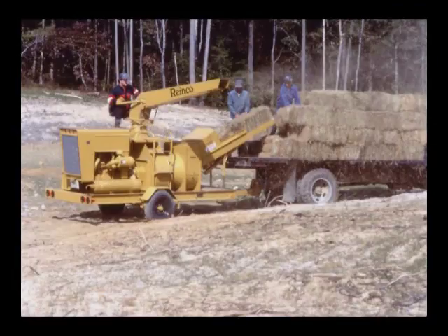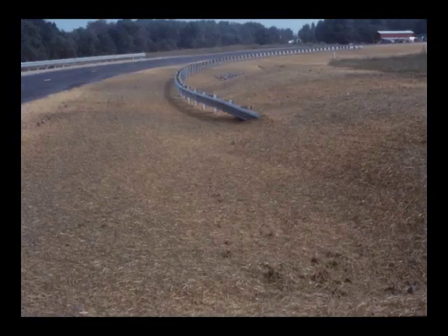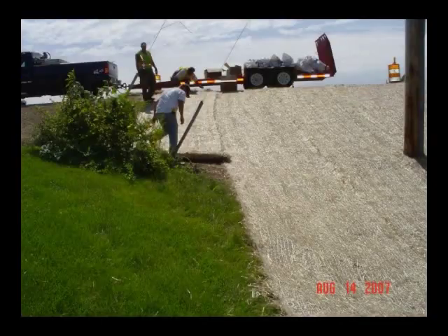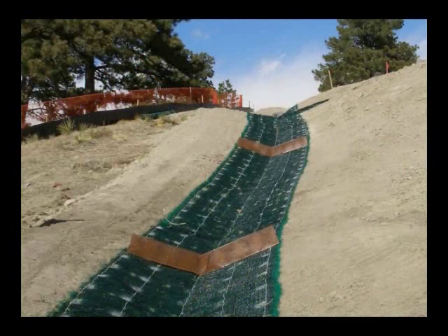On slopes, windy sites, or areas adjacent to roads, mulch must be anchored using netting, a tackifier, or a mulch anchoring disc. Many different combinations of mulch, tackifier, fertilizer, and seed can be applied with a hydroseeder. As an inspector, you must ensure that mulch is thick enough to provide adequate protection of the soil and is securely anchored. On steep slopes or in areas of concentrated flow, erosion control blankets or turf reinforcement mats may be required to properly secure the seeding.